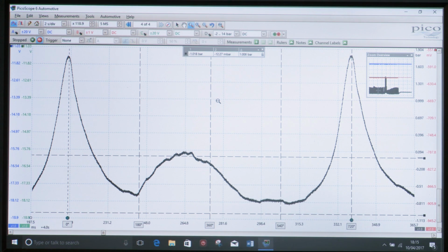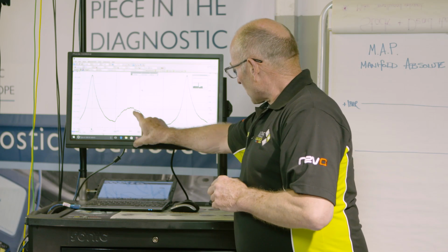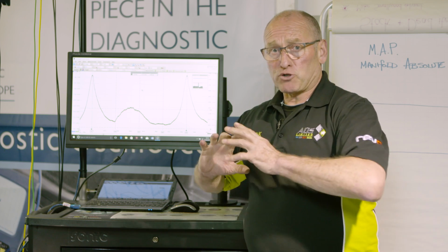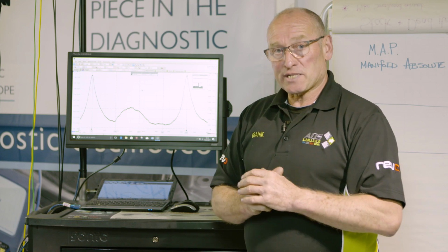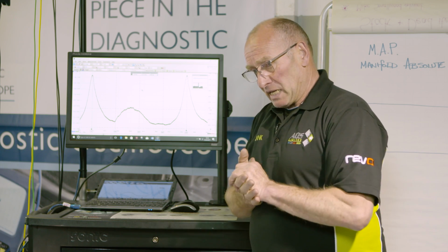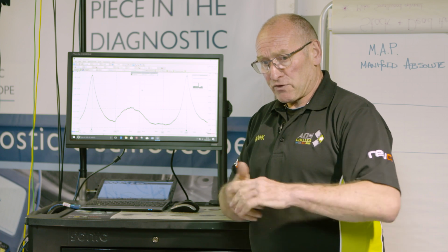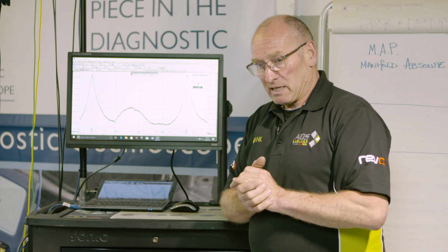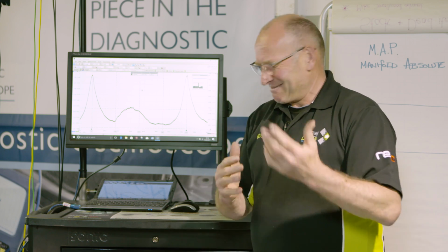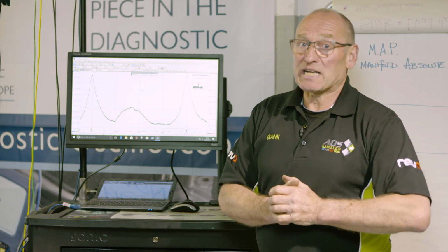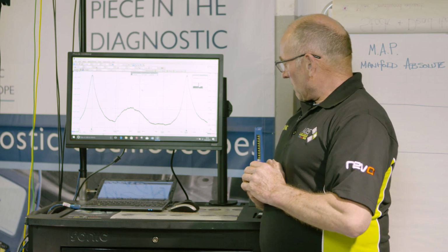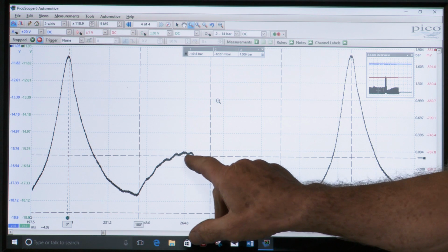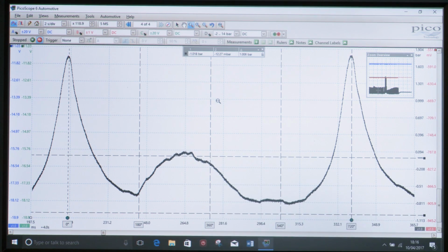I'm using these expressions quite carefully. So what does that represent? Well, it represents the pressure in the exhaust stream pushing the gases out of the exhaust system. And normally that would be somewhere around maximum of 3 psi, 150 millibar. It depends on the speed of the engine and the volume of gases, obviously. But there's a very minimal amount of pressure in the exhaust stream at that point.